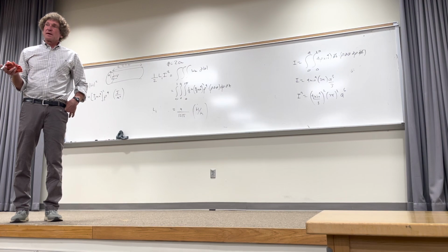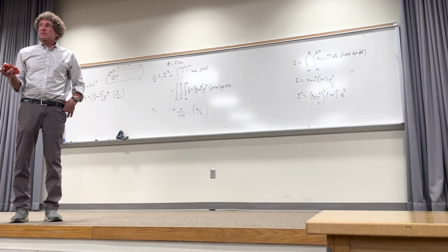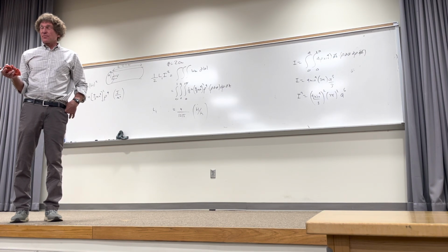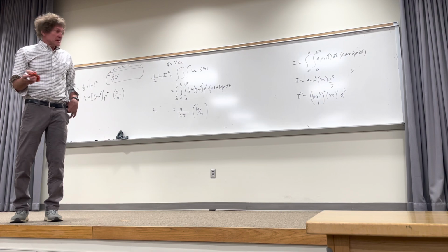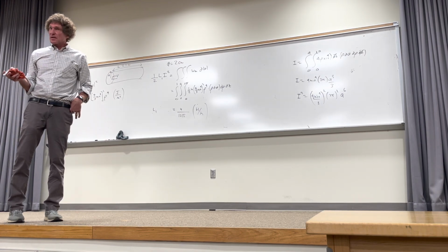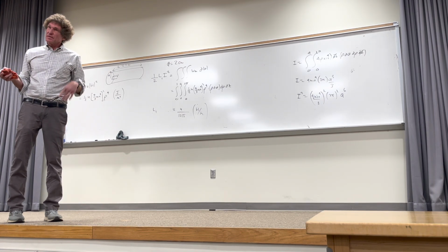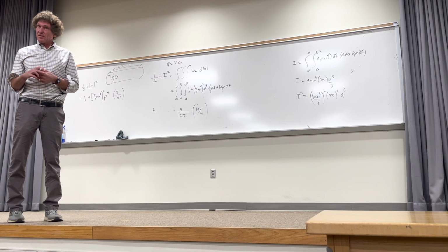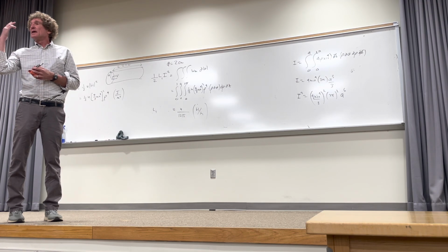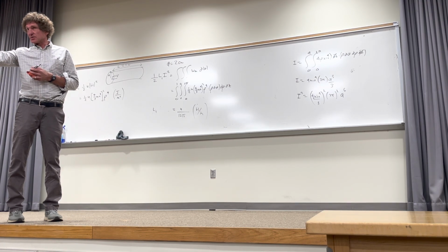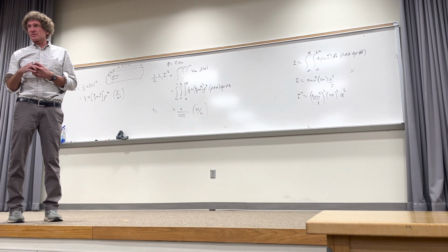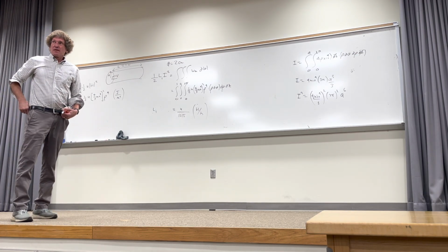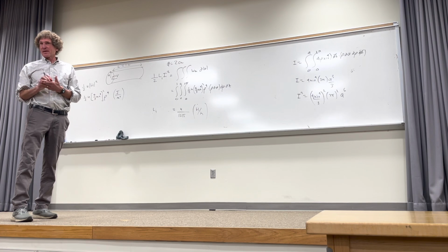Now, here's the one thing. What is the internal inductance of a wire if it's uniformly distributed? We did that last time. It's mu over 8 pi, right? This one's over 12 pi, so this is a little less, and it's caused by that gradient of current. The current is not a constant. It has a change to it. And this is just a problem that Wentworth came up with on his own.